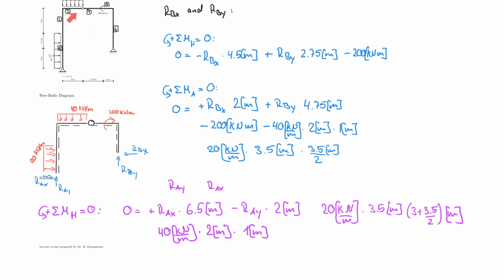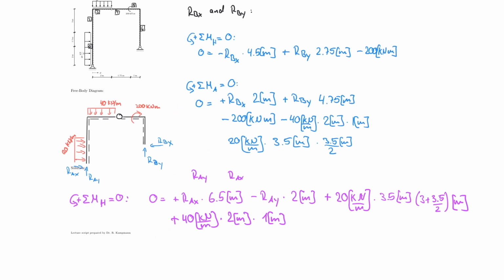All I have to do is to decide a rotational sense, which in this case is actually counterclockwise. We're rotating about this point. It's going down on the left of it, so it turns counterclockwise. That makes that positive. But by the way, we forgot the sign for this one here as well. Turns the same way around, so that is actually also counterclockwise. So they are both positive. And now I have that very first equation.